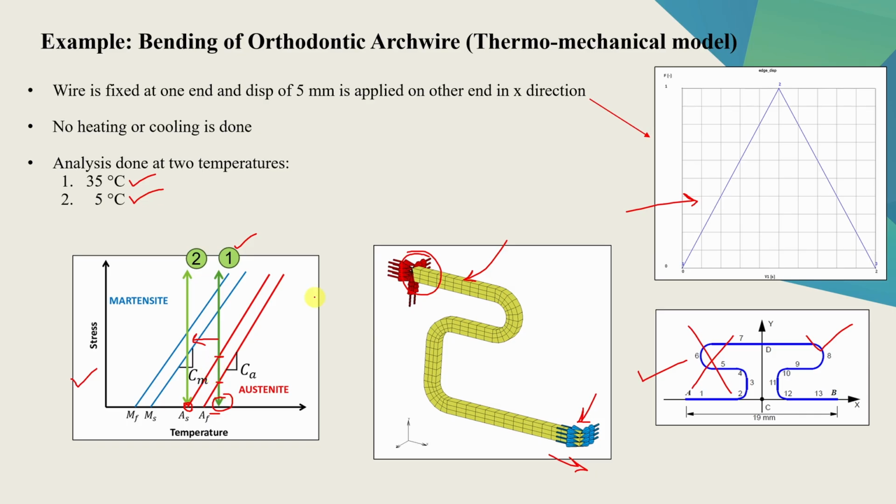One interesting thing to note over here is now temperature did not change. So we don't need thermal analysis in this. We don't have to solve heat equation. Only mechanical analysis is enough. Therefore, when our application doesn't involve temperature change and this vertical line is on the right side of this AF, so basically this area over here, then we can simplify the constitutive model by a huge margin. Like number of parameters also can decrease a lot, which is exactly what is done in Marc.